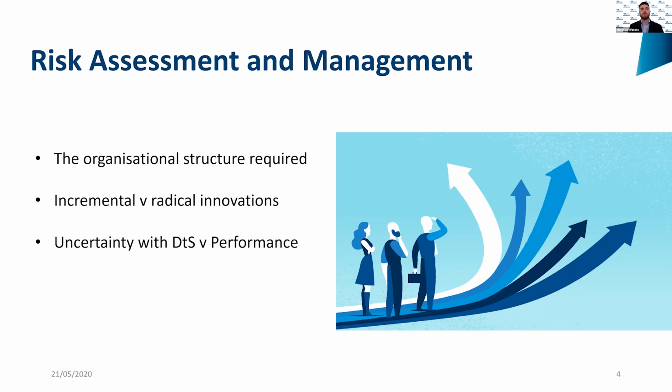If we consider the concept of risk a little further, it can be defined as the effect of uncertainty on objectives. Now, if we consider the application of this concept to performance solutions and DTS, we generally establish that there's a higher level of certainty with DTS provisions due to their deeming nature and the fact that we already know what the benchmark of compliance is. As we move to performance, the uncertainty rises, and therefore so does the risk level. So we really need to make sure that we manage the solution appropriately, and that's where the assessment methods, the evidence and documentary decision-making come into it.